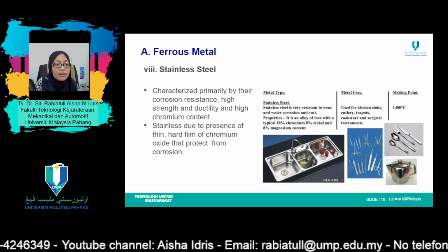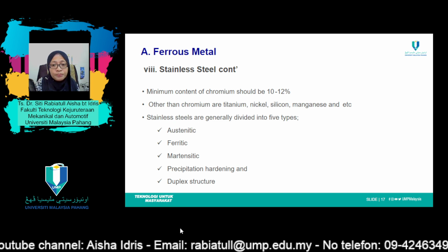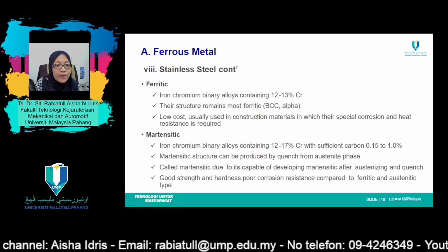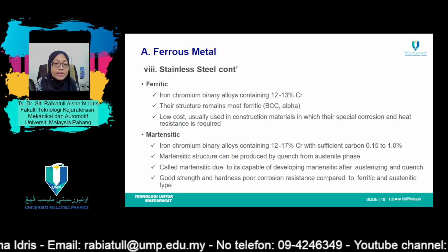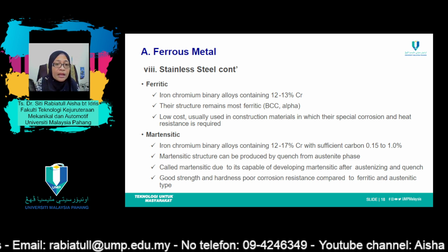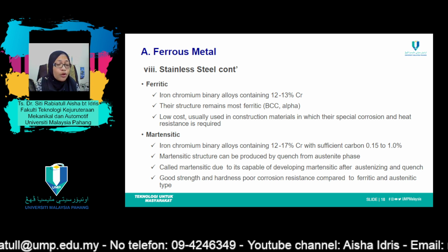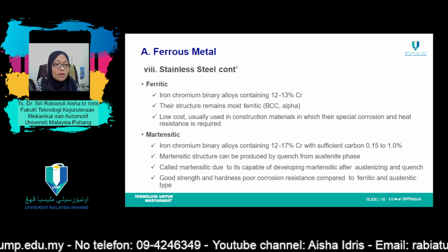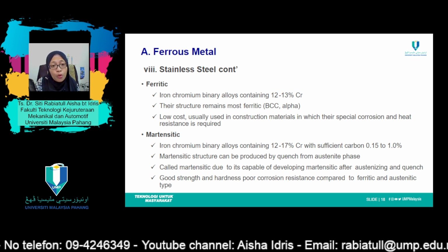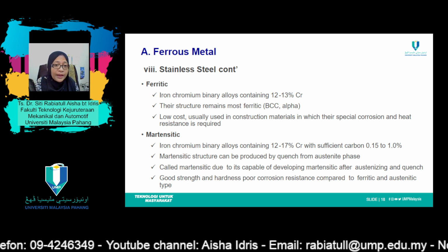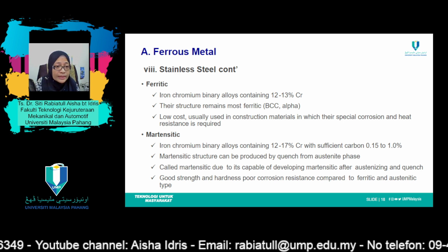Ferritic stainless steels are composed of the alpha ferrite phase. The austenitic and ferritic stainless steels are hardened and strengthened by cold work because they are not heat treatable. The austenitic stainless steels are the most corrosion resistant because of high chromium contents and also high nickel additions, whereby they are produced in the largest quantities.